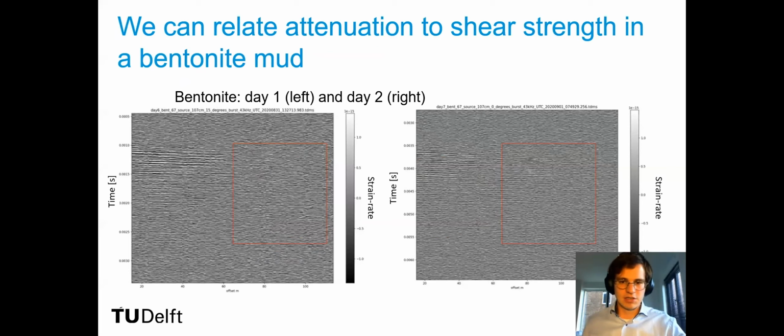In particular, we've demonstrated that you can measure the shear wave velocity, but more importantly, if you can actually measure the structure itself, the vibrations are modulated by the interaction of the structure with the soil, and therefore some of the concerns for offshore wind turbine structural health monitoring, such as the degradation of the turbine blades with wear and the erosion of the sediments around the base of the turbine with increasing use, will change the frequency content and strength of the Scholte waves generated by the structural vibrations because of the changing nature of the structural vibrations and the changing modal frequencies.